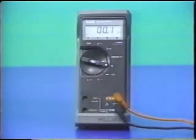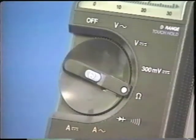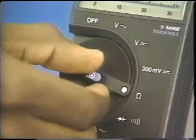Although you've just completed the basic setup procedures, let's take a moment to look at an important feature of the digital multimeter called touch hold. This feature simplifies the job of taking measurements. To activate touch hold, first turn the rotary switch to the off position.